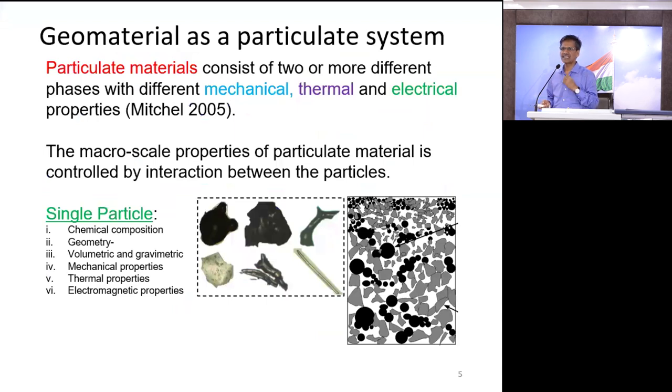In geotechnical engineering, I call it the geomaterial. If you read it as a 3-phase system, it is nothing but, I call it, particulate media. Like you might have heard about aerosol. Aerosol is also particulate media, but air is more, and water and solid particles are less. In this case, soil, my solid is more, then water, then air. Just the opposite. So that is also particulate media, and this is also particulate media.